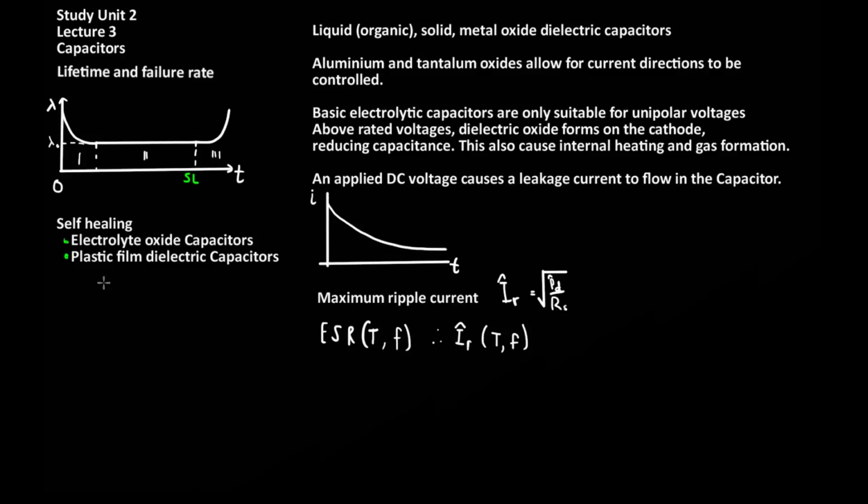In the case of electrolytic capacitors, the high field strengths will first manifest as defects in the dielectric. However, these high voltages will also allow for more oxide to grow and repair the damage in the capacitor. Thus, this will allow the electrolytic capacitor to self-heal.